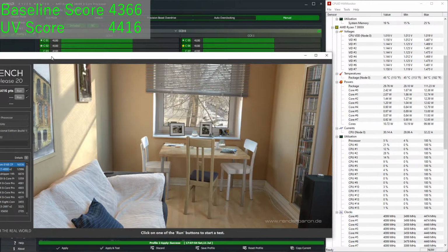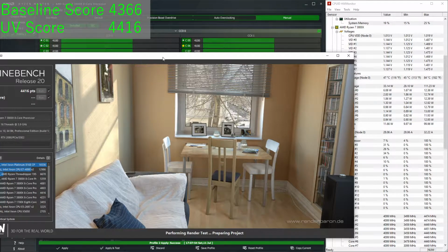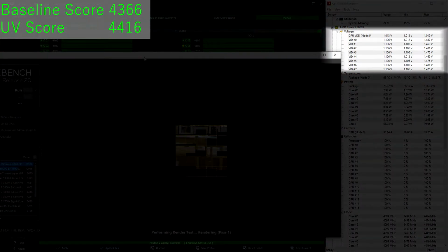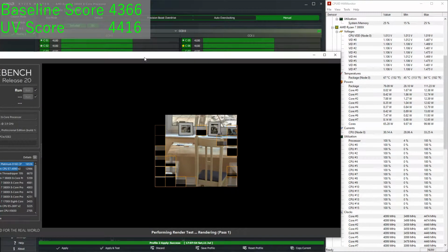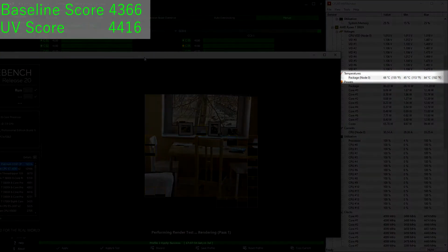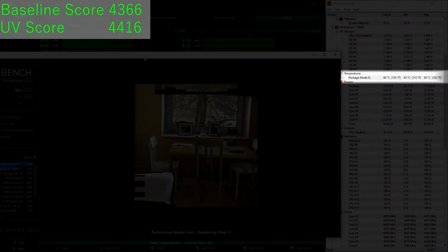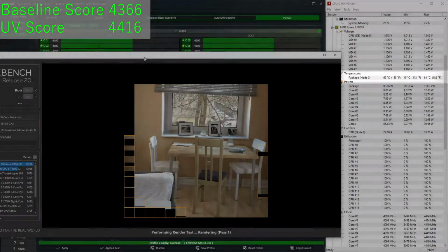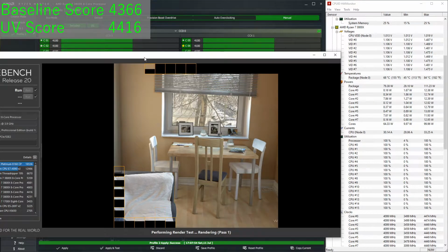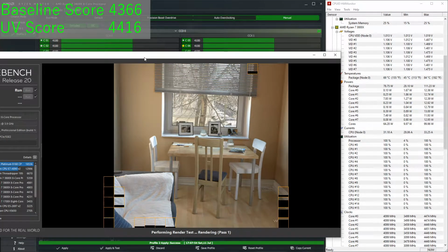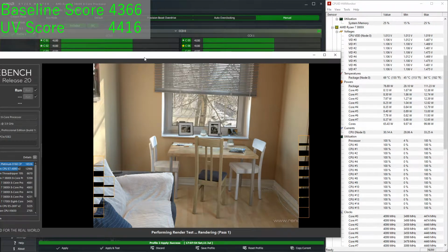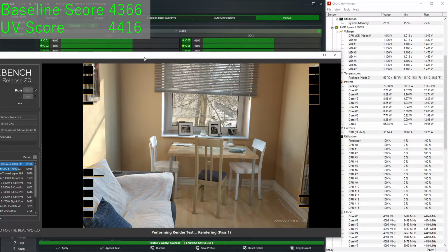Again, we see the load line do its thing and decrease our voltage even more. At the 1.1 volts we are effectively getting now, the processor is taking 0.15 volts less than stock. That translates to around 25 watts less power and 15 degrees Celsius less heat, as we don't seem to exceed 70 degrees Celsius down from the initial 85. We repeat this process as far as it will go, with the obvious stopping point being performance loss or even a system crash.